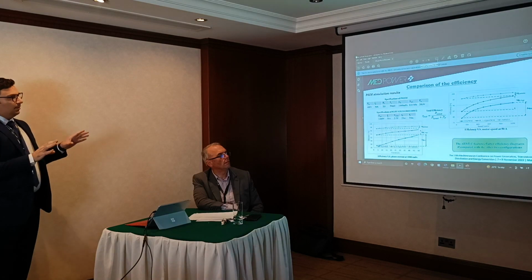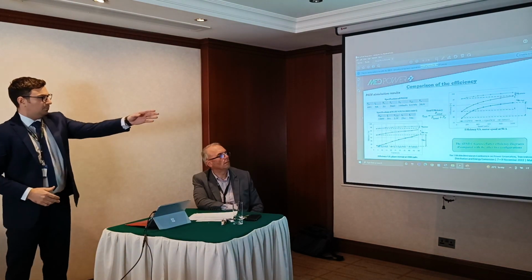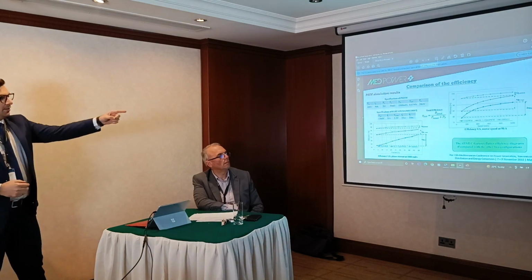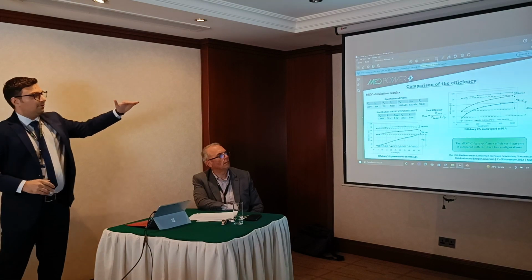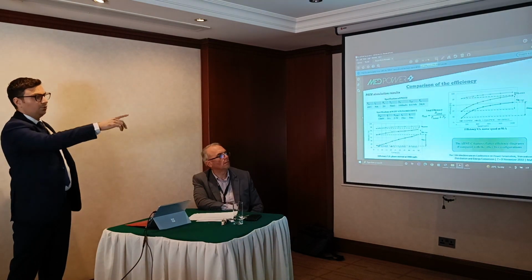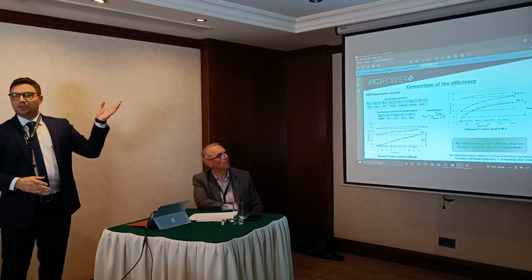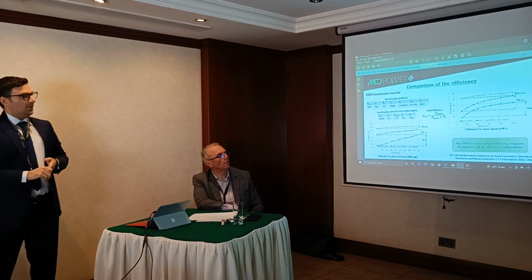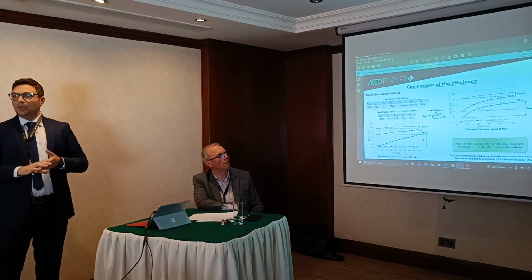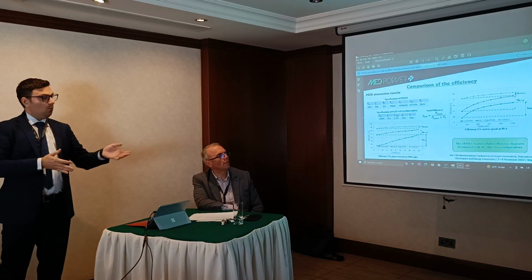So if we see these preliminary results about the efficiency versus speed and versus current, we note that the asymmetric hybrid multilevel converter features a flatter efficiency diagram compared to the other 3-level T-type and 2-level. This is an important result because this means that I can have high efficiency for both high speed, low speed, high load, and low load.